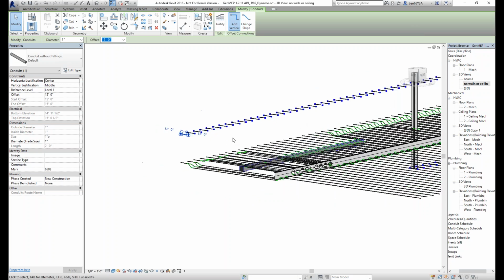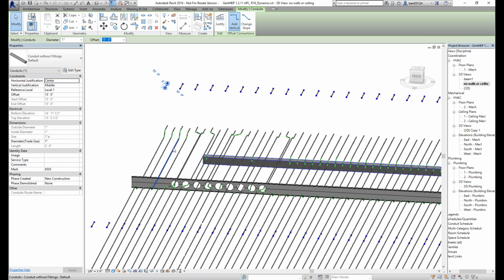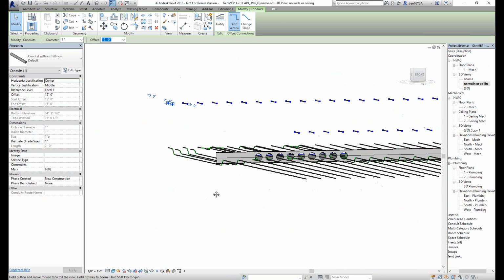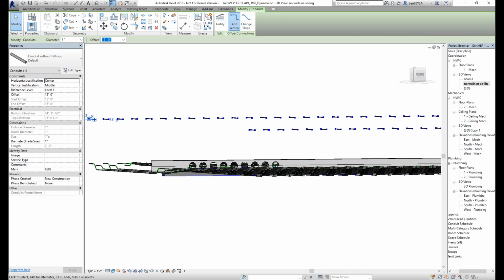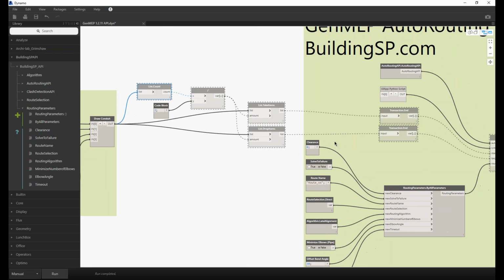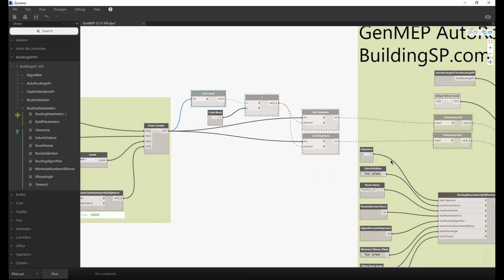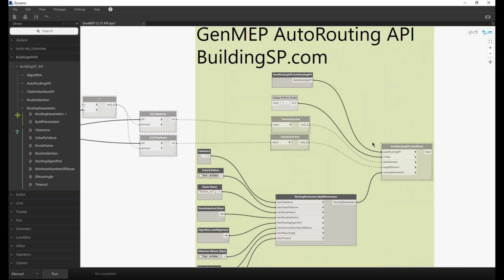And then the last step is feeding these 49 start and target stubs, just like Jack showed you. I just generated them in Dynamo, and now we feed them as a list. I break them back up into two lists of start and target, because in the draw conduit step they were all drawn in one swoop. So I split the list into two: the first half are the start points, and the second half are the target elements.